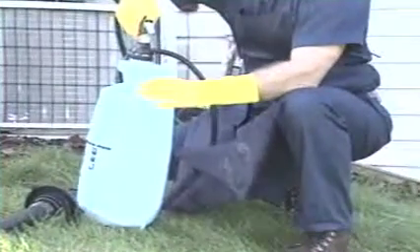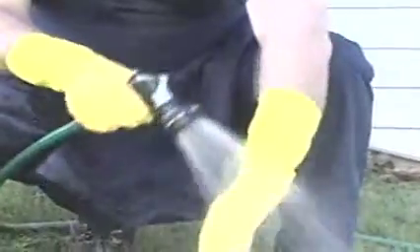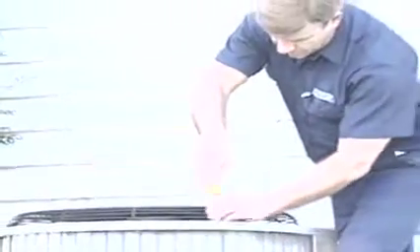After the cleaning is done, rinse the sprayer thoroughly. Clean any spills from protective clothing and accessories, and wash thoroughly. Now that the coils are clean, replace the fan and grill cover, remove the lock and tag, and turn the fuse disconnect back on.